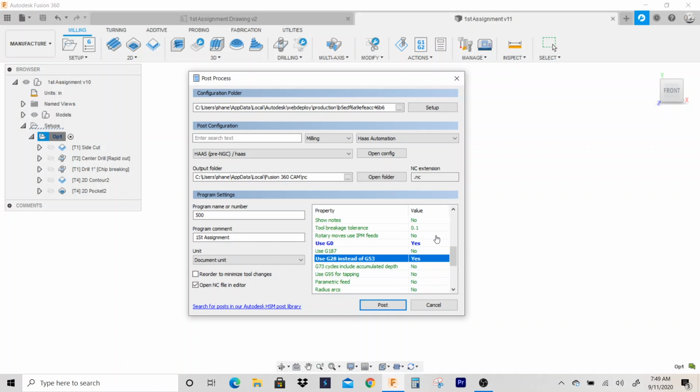You can't do that if you're using high feed rates, because you would have to override your feed rate, which would be annoying because you'd constantly be jumping back and forth from 100% to slowing down your feed rate for each move. If it's moving out for clearance using a high feed rate, and then coming in and engaging the material, you don't want to be jumping back and forth on your overrides. It's just a lot easier using G00.